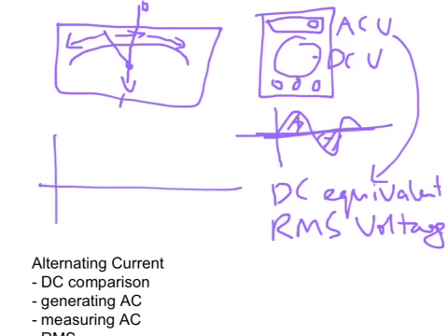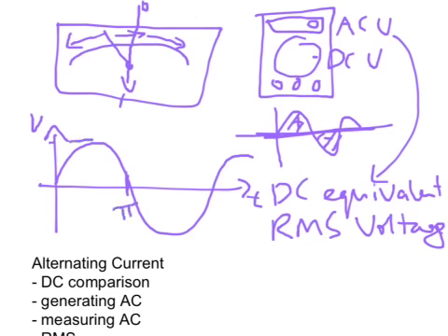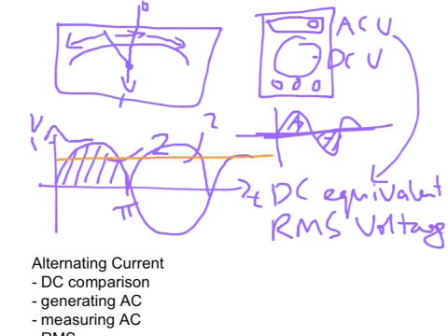So how we arrive at the RMS voltage is, if this is your sine curve showing the voltage against time as the voltage changes. For a sine curve, this is pi, and this peak is 1, and interestingly enough the area under there is 2. So you've got a whole lot of these humps with area under them of 2, 2, 2, 2, 2. We want to find a DC equivalent that just gives us a nice steady average, and this turns out to be more useful for power calculations and things like that.